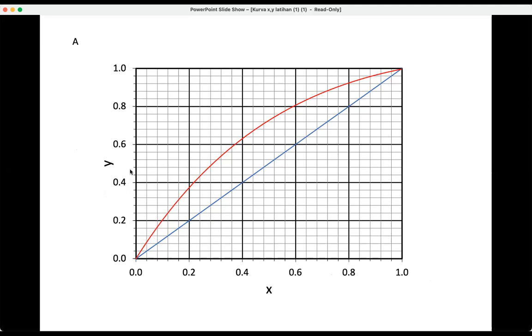So okay, so from here, where is mine? Yeah. Okay, so we find the Q line. This is the XD, and then this is the XB. And then we find the minimum reflux, and then you got around 4.